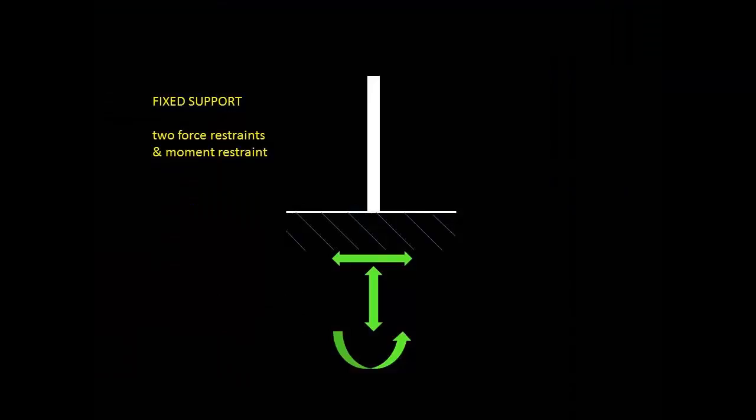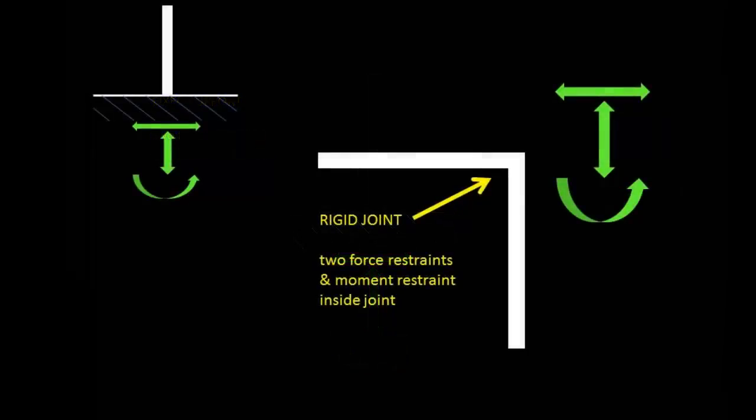In our structural analysis, when we draw members with continuous lines at joints, no circles, we will take it as rigid. For supports, a member buried into crosshatching, like the pile buried in soil, will be considered as rigid, with no translation or rotation possible.